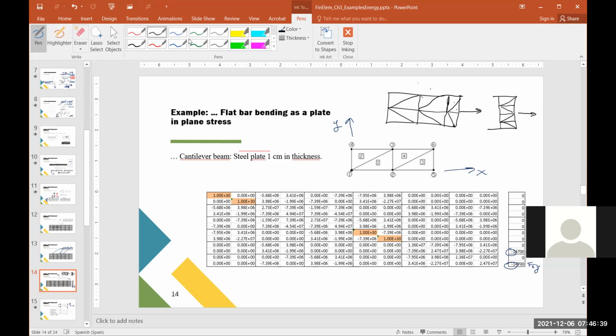So yes, you have to be very efficient in trying to partition your domain in such a way that it represents adequately the high gradients in the areas where you expect to have a large gradient, and in the areas that are very far from that, you can increase the size of the elements because those areas are not that important.